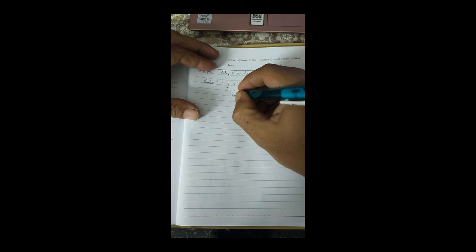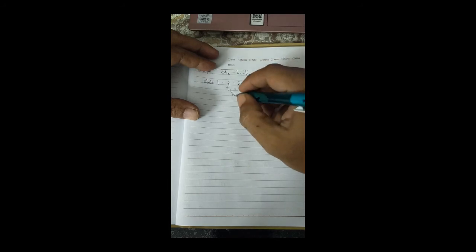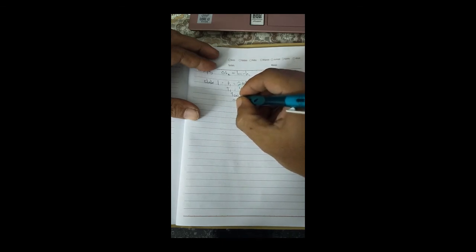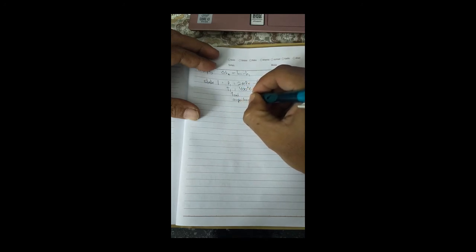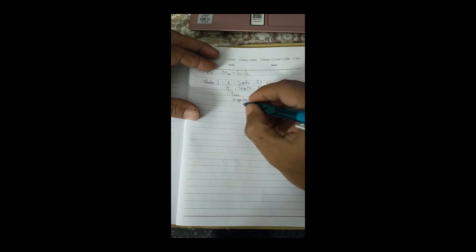Check your Tsat. If T1 exceeds Tsat, it is in the superheated region. As Tsat is much smaller than T1, it is in the superheated region. So get your H1.